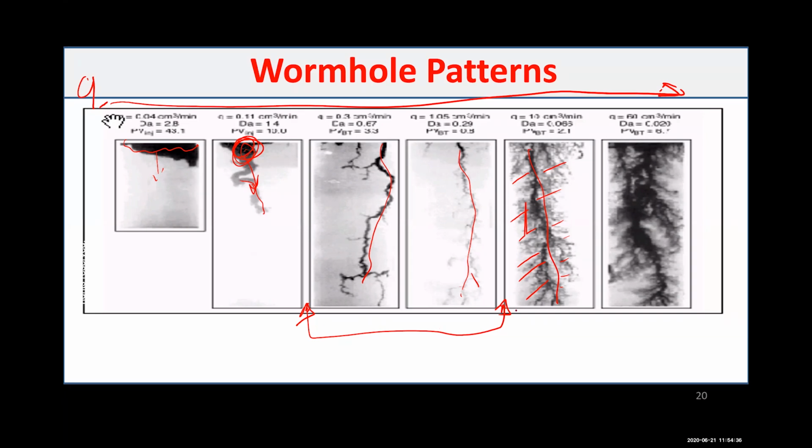Also, if you go away from the optimum, you pump a lot of acid, but you only need a certain length for the wormhole to dissolve. So you do not get any additional benefit. All the acid that dissolves more, you remove the oil, you remove the rock, but you actually do not get additional benefit in the permeability part.